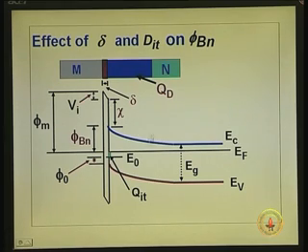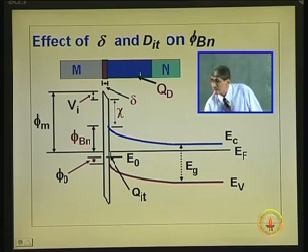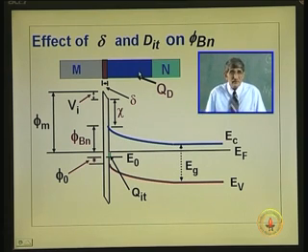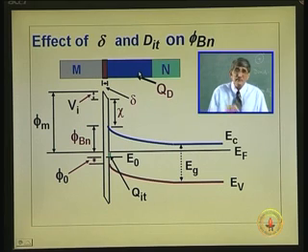You find out what is the charge within this side. Q is equal to C into V, simple law of high school. Charge is equal to capacitance times voltage. So, voltage difference is charge at one plate divided by capacitance between the two plates. So, I can find out this drop V I as the charge present on this side of this oxide or dielectric divided by the capacitance of that layer. And what is the charge? Initially, if there is no interface state density, charge is only due to Q D, the depletion layer. Now, there will be charge corresponding to the interface state.